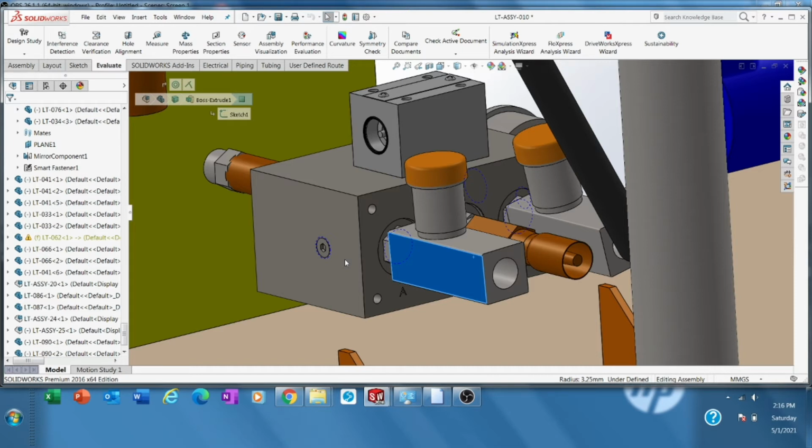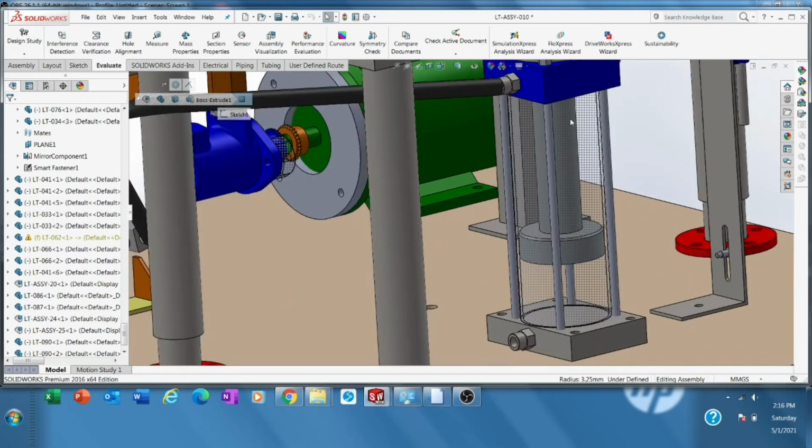It's very, very small, 0.1 millimeter. So we have to ensure that the oil from that direction can move back to the tank, so that this area can be occupied with incoming pressurized oil. So how does it go back to the tank?